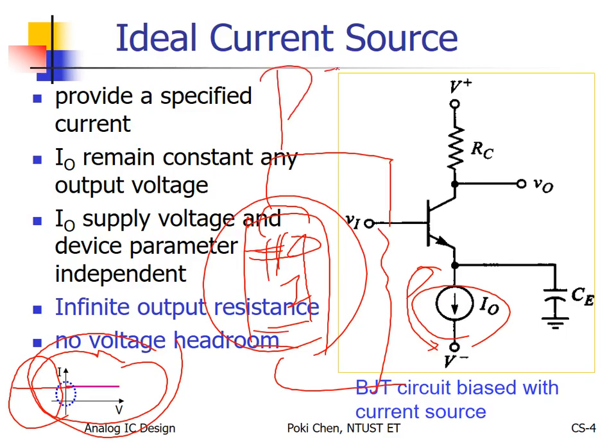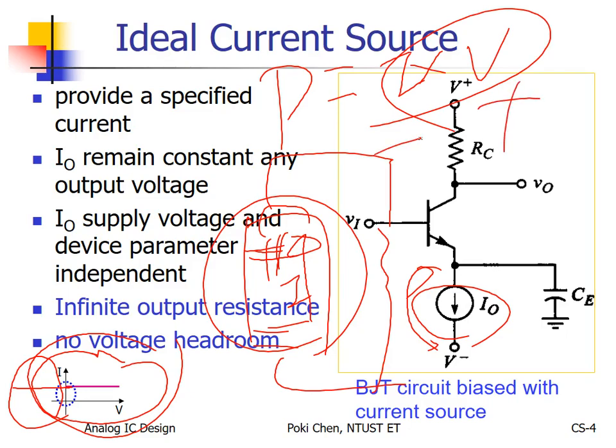So according to P equals IV, that is positive, that is negative, you have negative power consumption. What does it mean? Power consumption is usually positive, right? For a resistor, positive here, negative there, so the current flows this way. Both are positive, so you consume positive power. It makes sense. But if you consume negative power, it means you generate power for the others. So you become a battery.